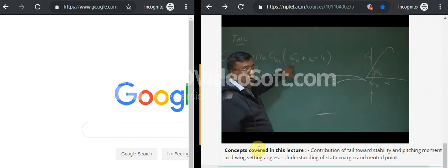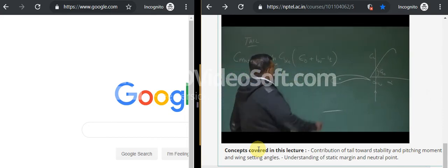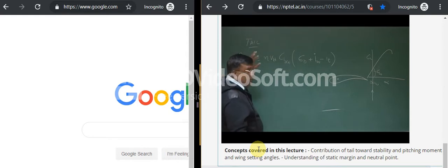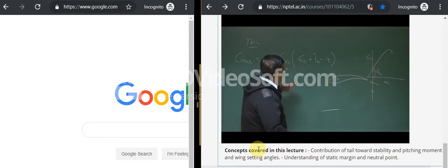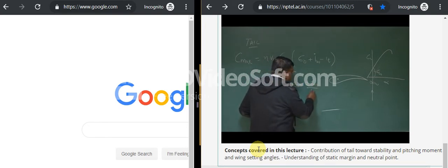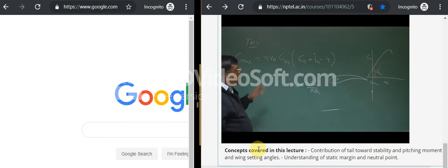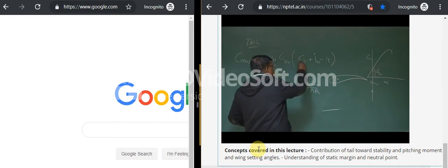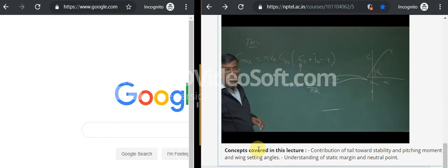Okay, what is Iw? Iw was the wing setting angle, and It was the tail setting angle. Now from here you could see, if there is a cambered aerofoil wing, some value of epsilon naught will automatically come, which is 2 Cl naught by pi aspect ratio. I am assuming E to be 1 roughly. So if there is a cambered aerofoil wing, that will give some value of positive epsilon naught. Okay. Right. What about Iw?